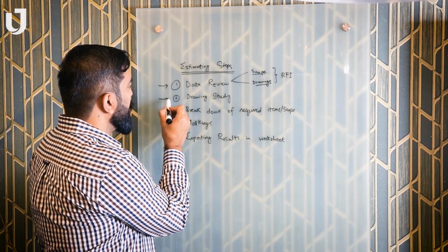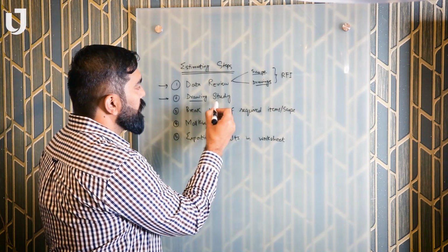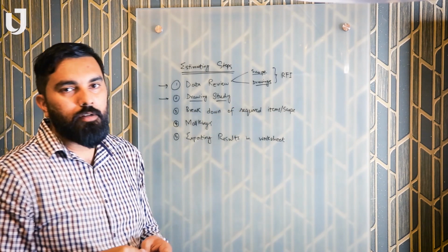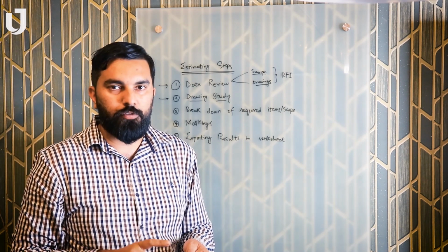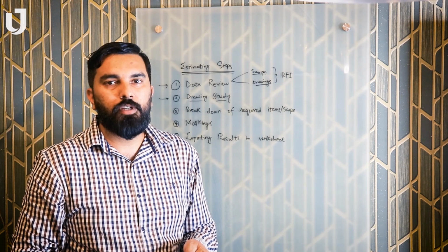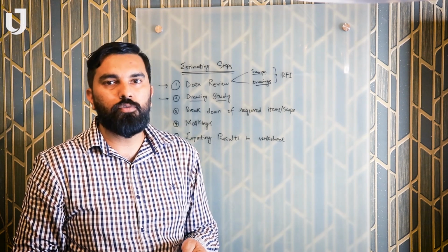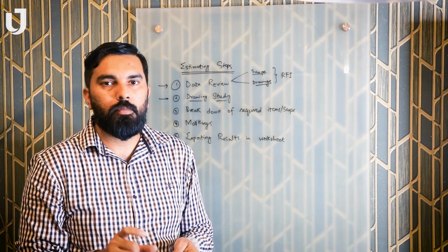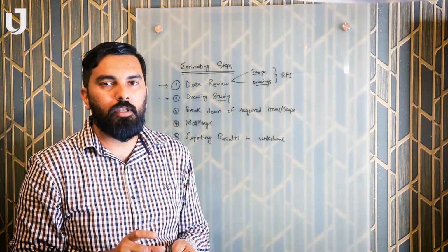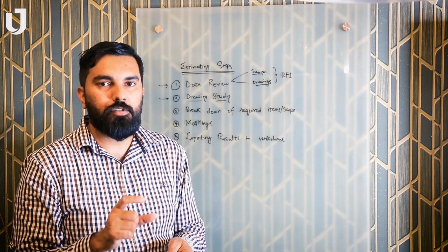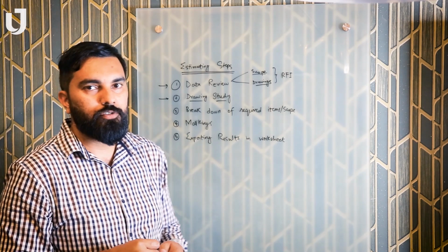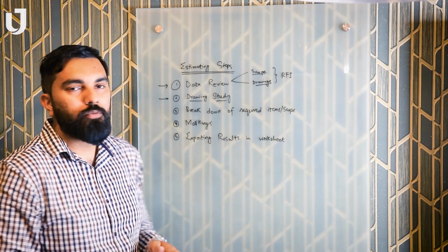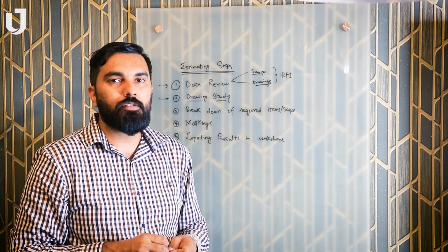The very important step is the study of the drawings. If the estimate is going to take around maybe 4 to 8 hours, you have to spend at least 15 to 20 minutes reading the drawings to save you some time. If normally you are spending 8 hours, you can save 2 hours by spending an extra 20 minutes studying the drawings, just to familiarize yourself. You must visualize what the drawing is saying.